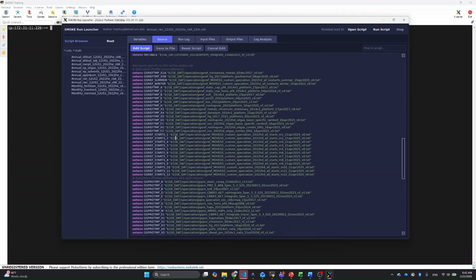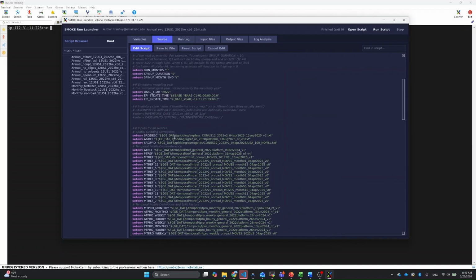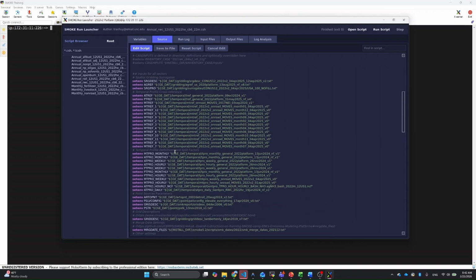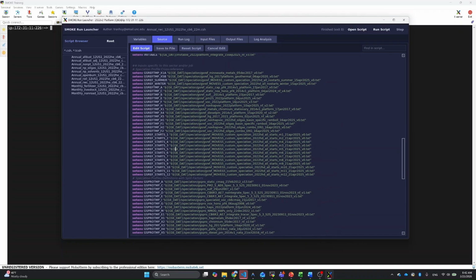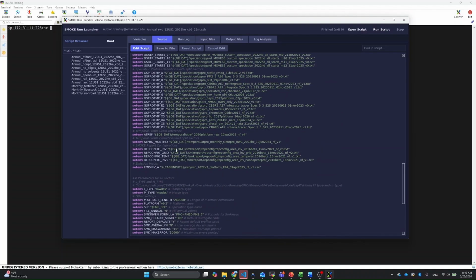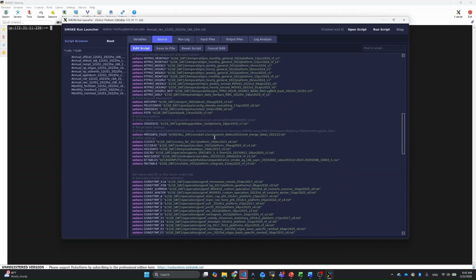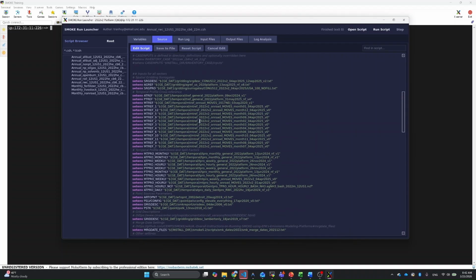Now, if you notice, there is another ATDREF defined in the earlier sections of the SMKRUN script. The way that C shell or T shell script operates is that any later setting of the same variable will override its earlier setting, meaning at this point the ATDREF will be overridden with this particular setting, pointing to this particular file, and override the setting in the earlier ATDREF.